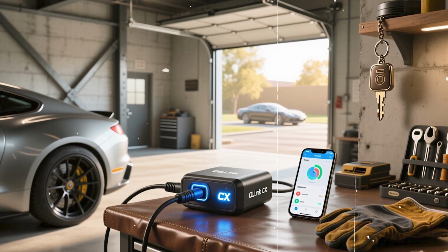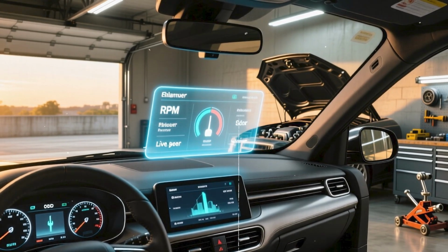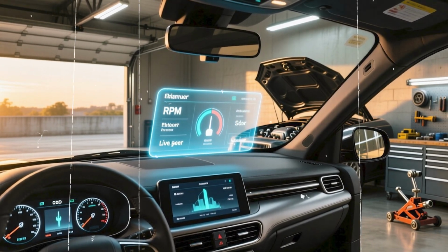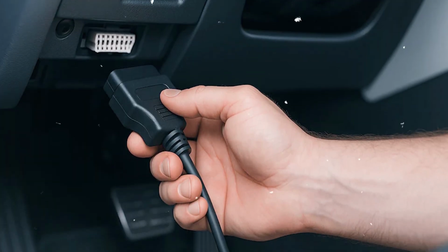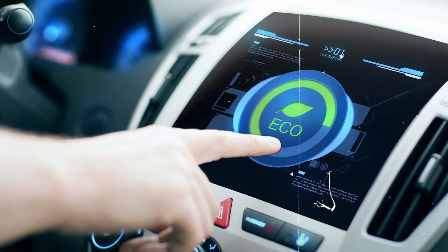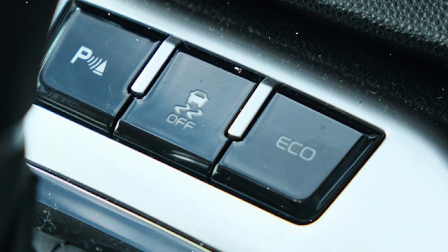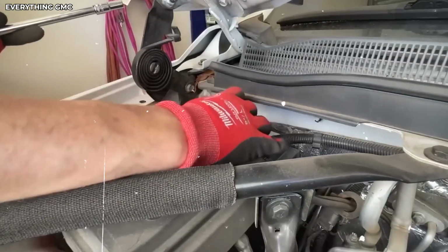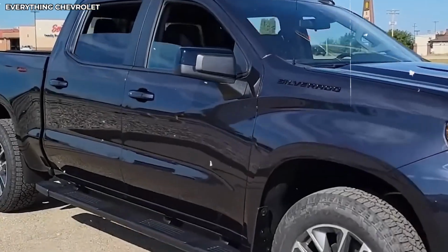Connect your OBDLink adapter to your laptop's USB port and to your Ford's OBD2 diagnostic port, which is located under the dashboard on the driver's side near the steering column on most models. Turn your Ford's ignition to the on position without starting the engine. Launch ForScan and let it detect your vehicle. It will identify your specific model, year, and all installed control modules. This process takes about 30 seconds.